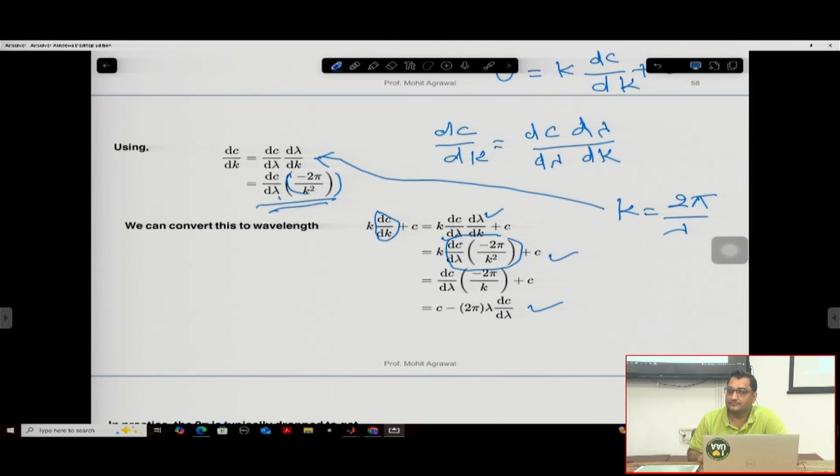Any question? Sir, with respect to earthquake magnitude, whether the shear wave velocity changes with respect to its magnitude? No, that is not a function of the magnitude, because that is the elastic parameter of the soil. So with respect to magnitude, the velocity of the shear wave in a material doesn't change.